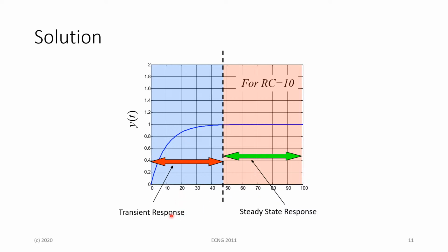So basically, for any typical system, you will always have an initial transient response once the circuit is switched on, and then a steady state response at which the system will be stable. Now this holds true for stable systems. You'll see later on there's something known as an unstable system where this does not hold true, and we'll discuss that at length when we reach that point in our lectures.